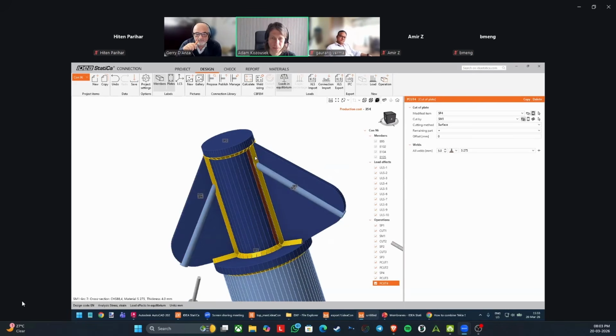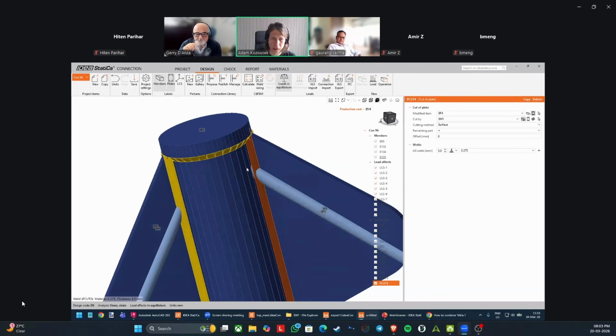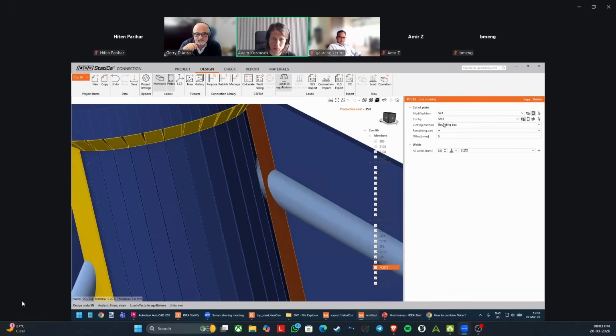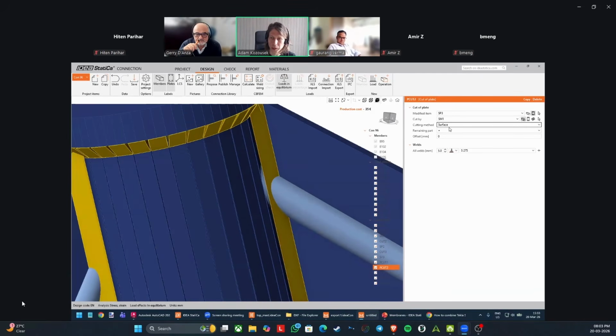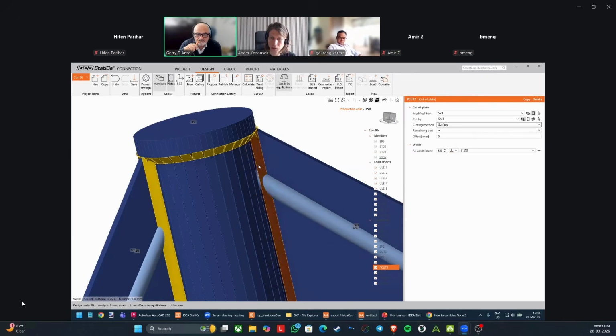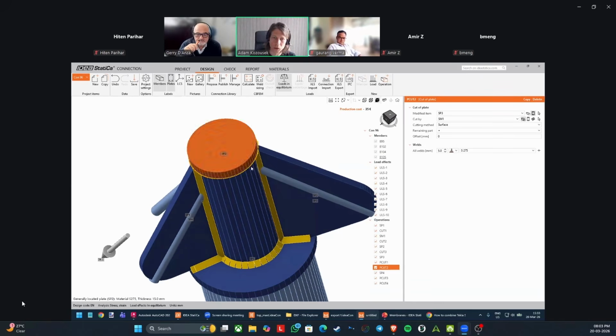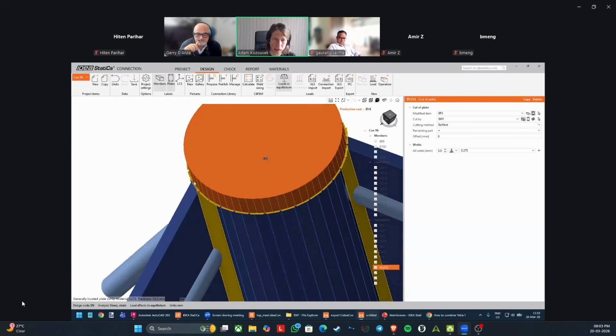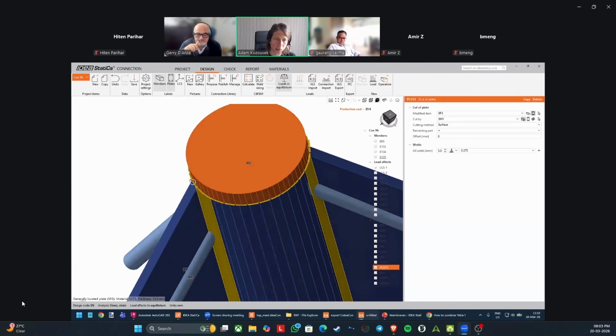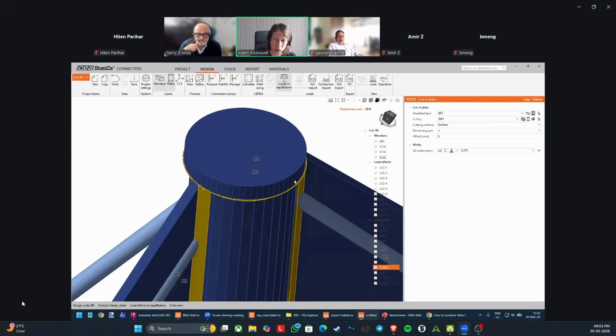All right. So I will just go back here. You can see if I switch here to surface, it moves a little bit. It's a very tiny bit. So the bounding box goes around here. At this point, it's very close to the tube, but at this point on the other side, it's a bit farther, so it didn't do the cut. So that's why it's better to use the surface.